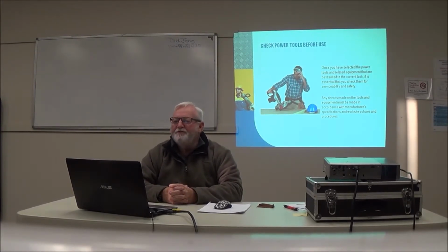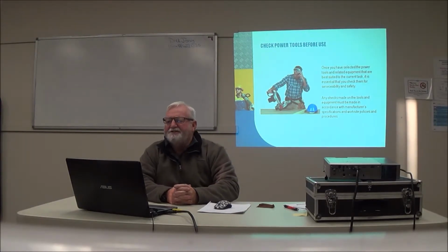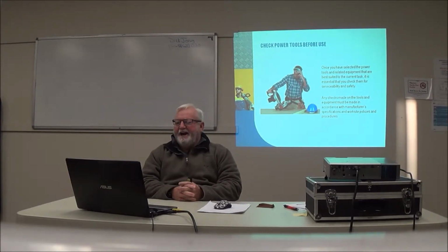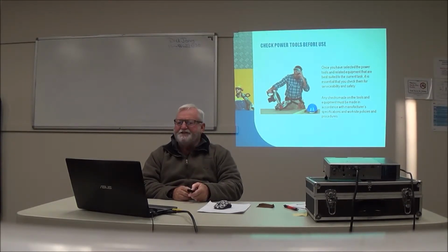Check power tools before use. Once you have selected the power tools and related equipment that are best suited to the current task, it is essential that you check them for serviceability and safety. Any checks made on the tools and equipment must be made in accordance with the manufacturer's specifications and worksite policies and procedures.